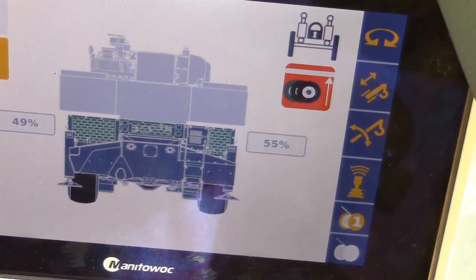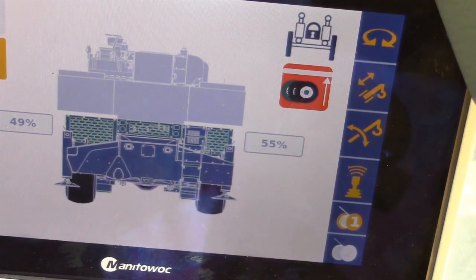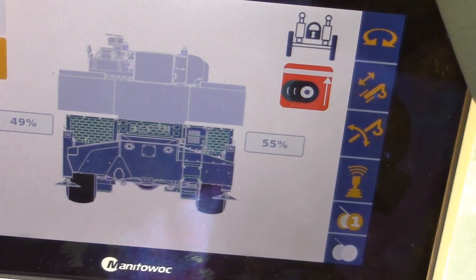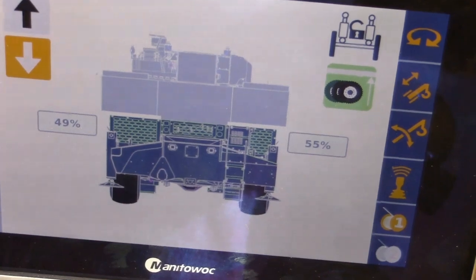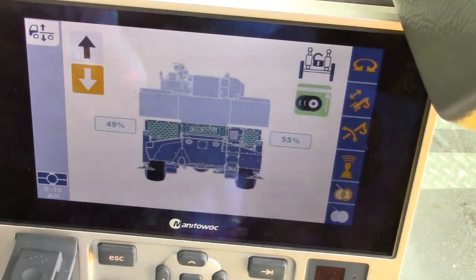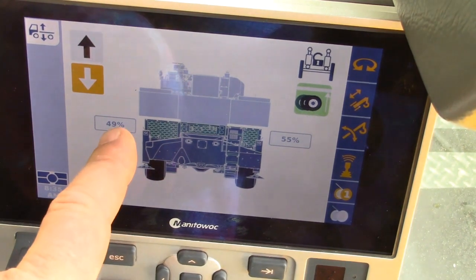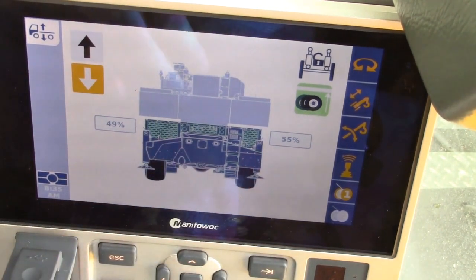I'll go back to the RCL now and select a proper rigging code of 9016, which is over the front plus or minus 2 degrees with full counterweight. We can now see that our symbol has changed from red to green, symbolizing that we are at ride height within the 10% difference of left and right side suspension control. Each sensor needs to be within 10% of 50, so we could have a possible 40 and 60 and still be somewhat within the tolerance.